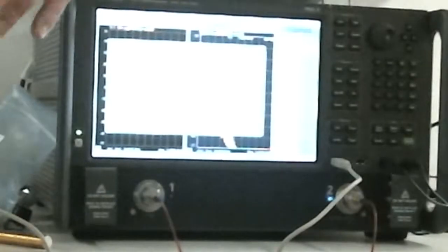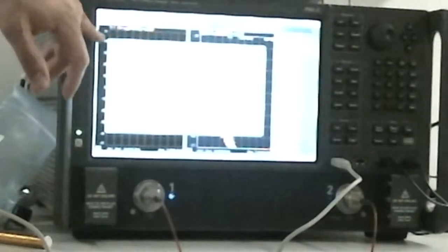So you can say S21 times S12, with the cosine, sine, all the basic math functions that you have access to. You can look at just the complex. You can do exponentials. You can do the impedance. You can do powers. You have access to, like I said, pretty much a full math suite. And what this does is it'll take whatever you do, you'll call this variable whatever, and you can say plot this.